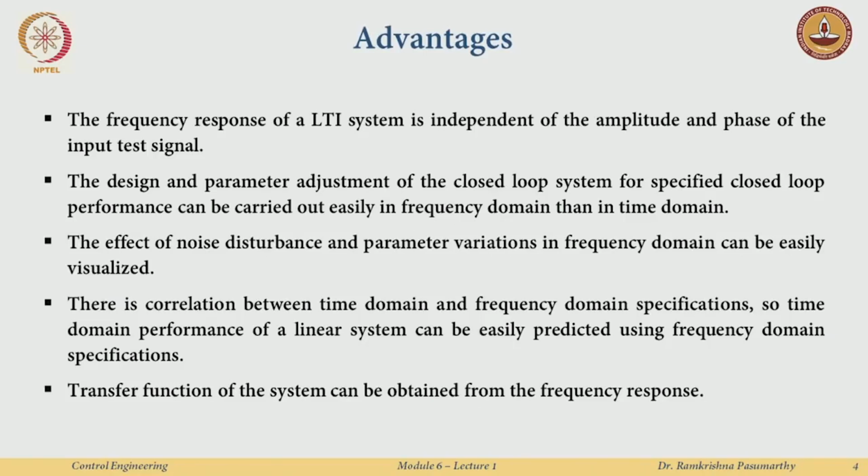So, why do we need to do all this analysis? Most of this analysis, which we also call the frequency response, is independent in a way of the amplitude and phase of the input test signal, and we will see why that is true. When I go to design a certain system, the design and parameter adjustment of the closed loop can be carried out rather easily in the frequency domain compared to the time domain. So far we have not looked at design problems, but this will be obvious when we start handling design problems in the coming lectures.